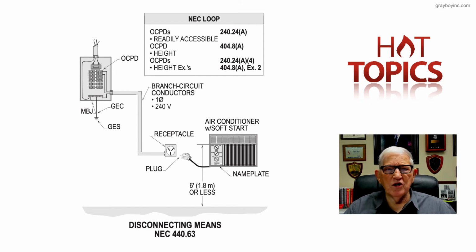Now, notice we show in the illustration the overcurrent protection device at the service equipment routed over to this receptacle, and it's cord and plug connected. Now, I suggest that you review 300.15(A)(3), approximately on page 146. Look at 300.18(A), approximately on page 147, and review that information there.